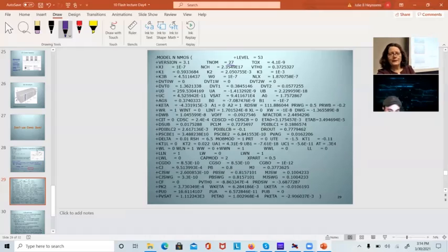So that was the whole thing: in order to verify that what we were doing worked, I had to get the transistor model right at our operating transistors, at our operating temperature. I couldn't just fudge it, because you can't fudge something like this when you don't know what you're doing. I had to go through and theoretically figure out what each one of these was, how it was affected by temperature, get an estimate of it, show the model in PSpice, and then take other transistors down to 35 Kelvin and verify their actual results matched my theoretical results. That was a pain.